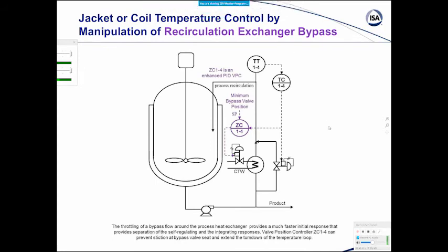Okay, now we often have control being done by heat exchangers and a recirculation line. We have a temperature controller there and the process recirculation. It's probably going to get its set point from a vessel temperature controller. That's not shown here. So we're controlling the outlet temperature of the heat exchanger. Hopefully this is not a very long distance here from the heat exchanger to that elbow.